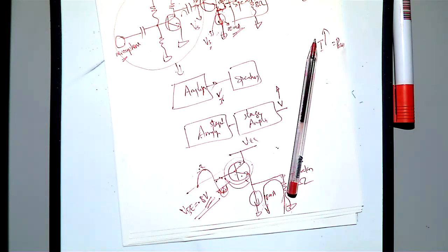So here this is your signal. This is your DC voltage, that is 0.76 to 0.8 volt. Usually you will make sure that your bias voltage here is 0.8, because your signal will be riding on top of 0.7 volt. This transistor will first be biased, and then you have a sinusoidal signal riding on the 0.8 volt. You know what I meant? Because you have to bias your transistor first, and then your signal will be riding on the bias.